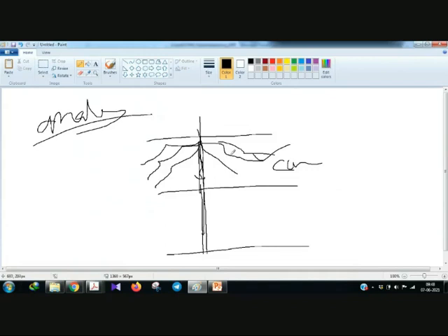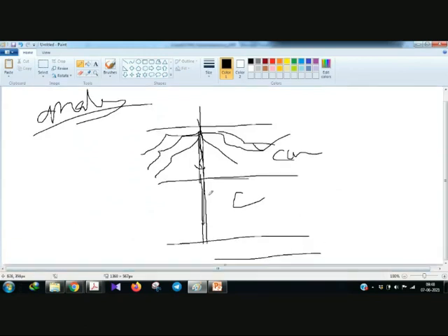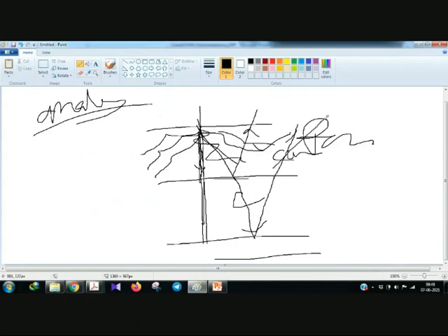But I'm not interested in the overburden. I'm interested in the layer boundaries below that. So the overburden should be resistive. If it's resistive, then it won't disperse like this. It will follow one path, and one portion will be reflected like this, and another portion will be reflected like this, then reflected like this. So this is how GPR works, and a conductive overburden is not acceptable here.